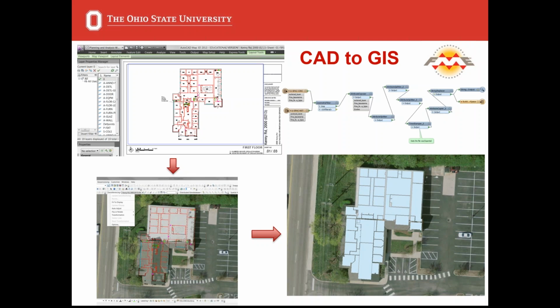So as far as floor plans and segueing a little bit into CAD to GIS, I think most universities are already very familiar with this. All of our CAD drawings were in 0, 0 space. So like many of you, we've also had to georeference those CAD drawings. We then utilized FME to port that data, the space identifiers in there, so that we can then link back to the space data system that we use here called SIMS.